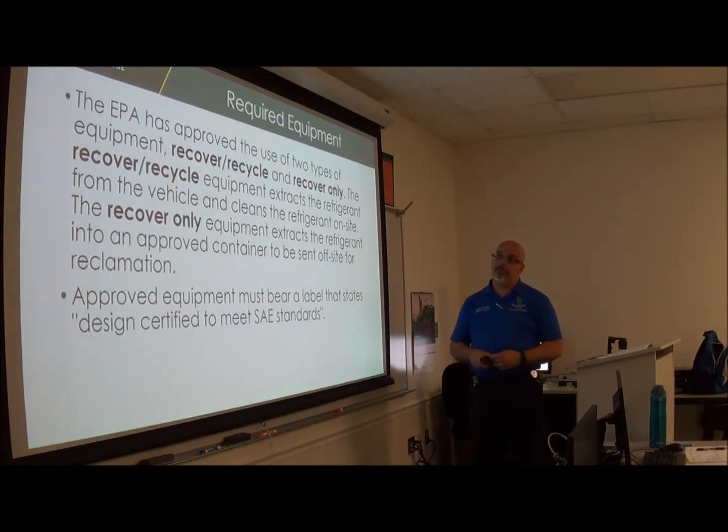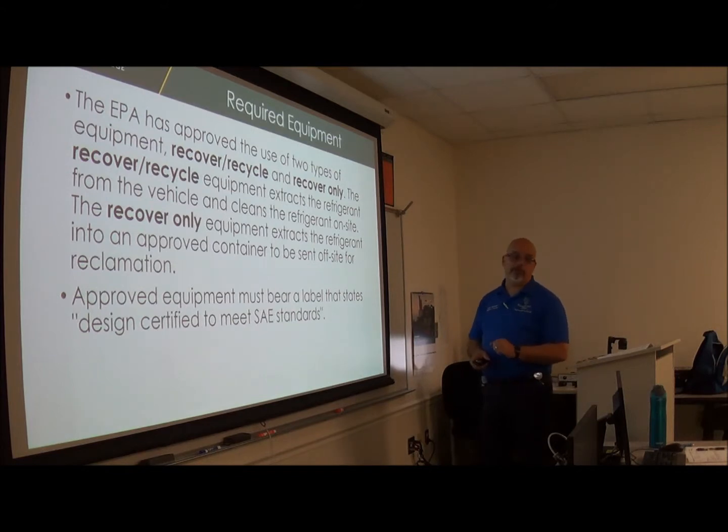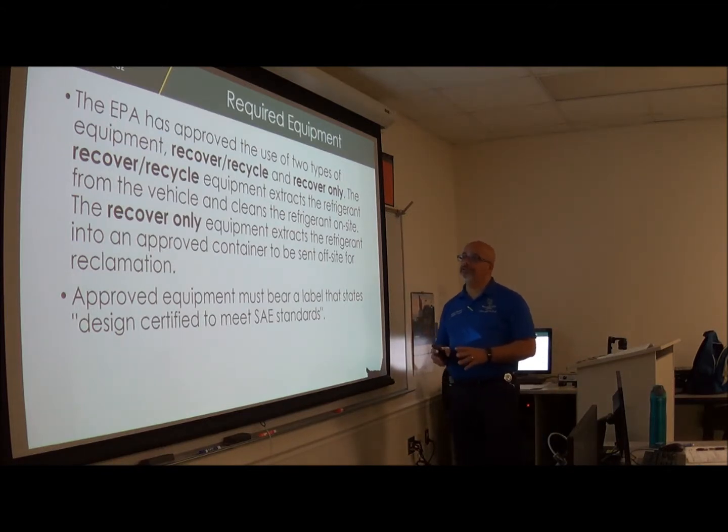Required equipment. The EPA has approved the use of two types of equipment, called Recover Recycle and Recover Only. The Recover Recycle equipment extracts the refrigerant from the vehicle and cleans the refrigerant on site.